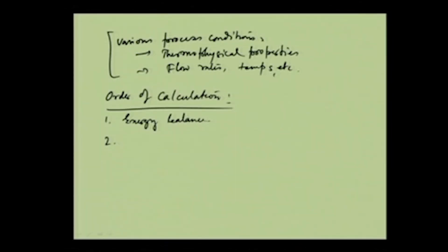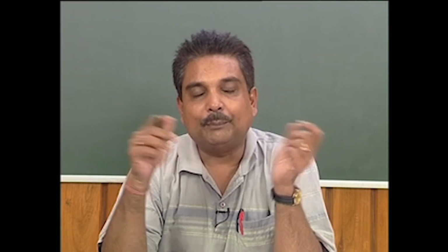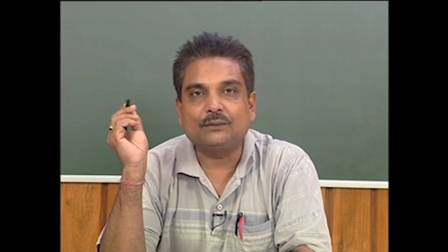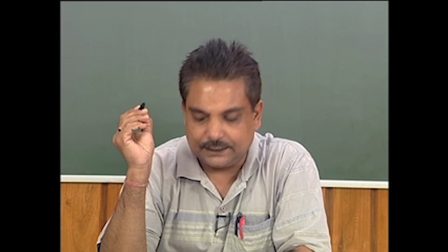Then we have to see the LMTD estimation, and in double pipe it is usually counter flow, because we have already discussed at some point of time that counter flow usually gives better heat exchange, due to maintenance of the uniform delta T all through the heat exchanger, and that is particularly true when we have a double pipe heat exchanger.